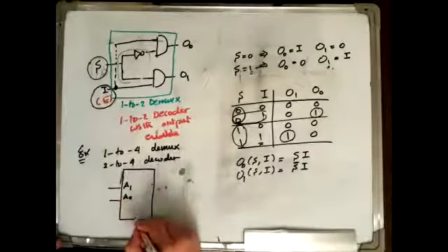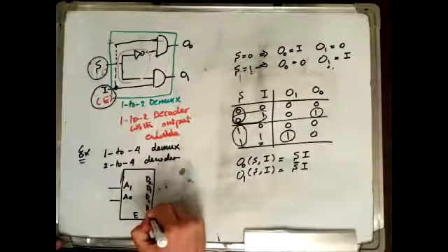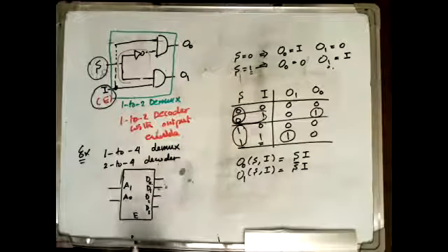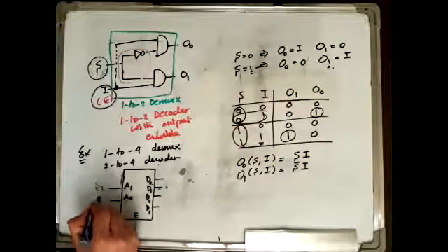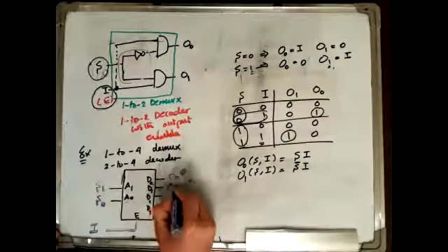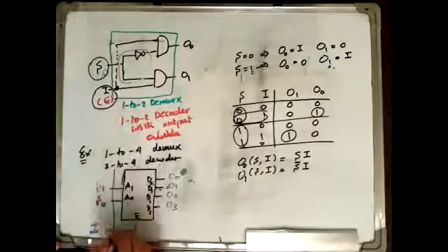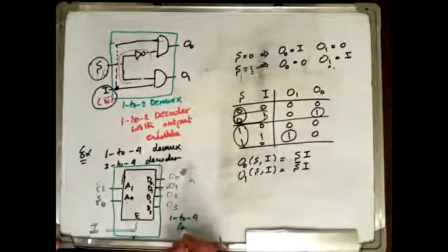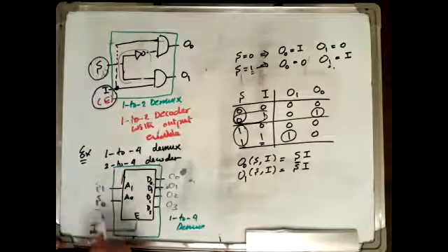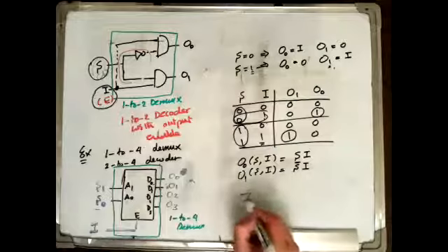So I will take a decoder. This is a decoder with A1 A0, if you remember, and here there is the enable, and here D0, D1, D2, D3. This is a decoder, but I can use it as a 1 to 4 Dmux by simply connecting the enable with the input, and A1 and A0 are basically S1 S0, and these are output 0, output 1, output 2, output 3. So if I do it this way, this becomes my 1 to 4 Dmux. Through the selection lines, I allow this input to appear either here, or here, or here, or here.